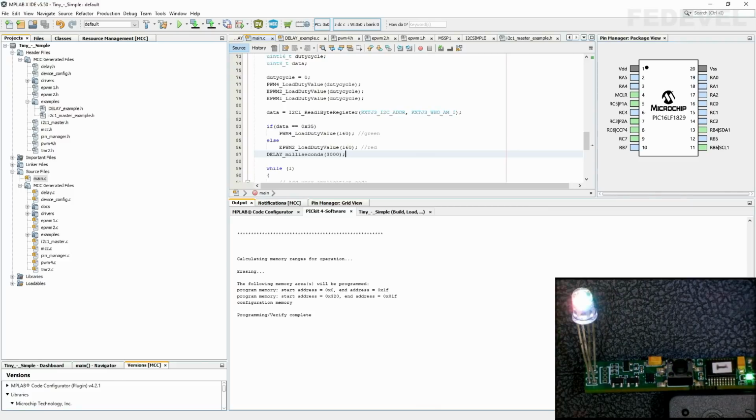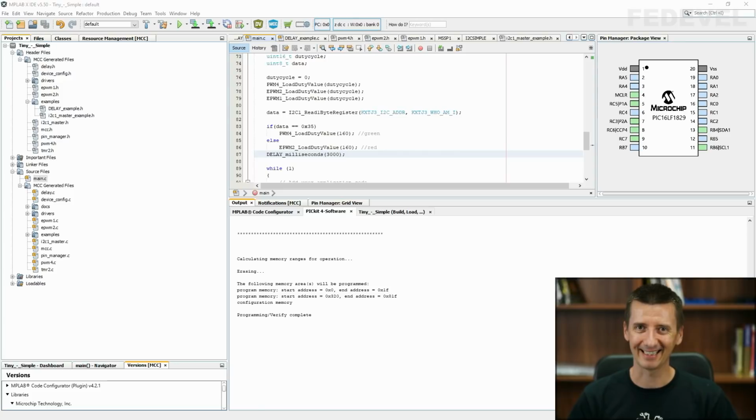If on your board you can see the green light, well done. If it doesn't work, if your LED shows red, then you may need to do some debugging. And the very first thing what you may want to check is how well the accelerometer chip is soldered down, okay? Because this was my case in my test boards.